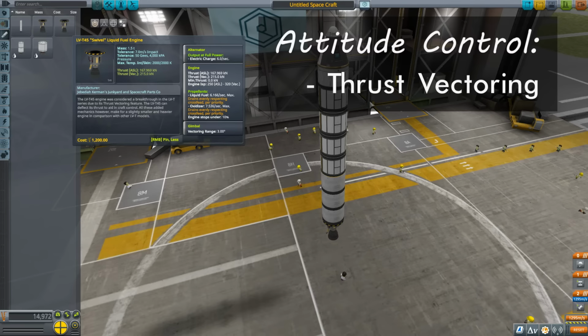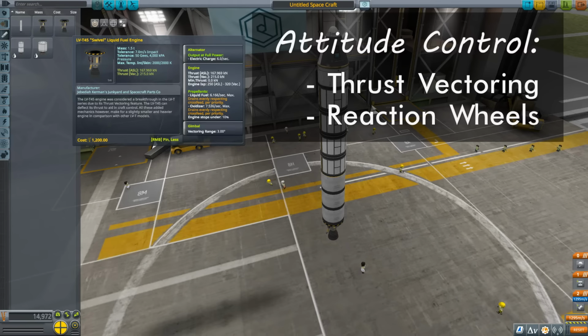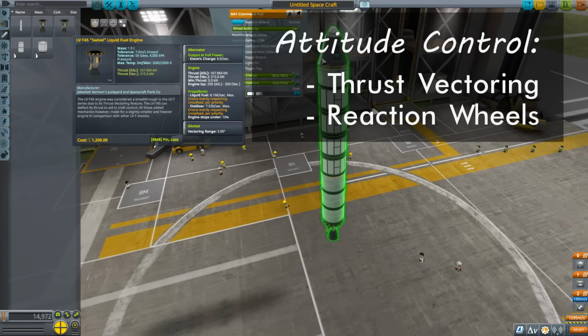Another way that you have is through reaction wheels. Reaction wheels are very heavy wheels that are spun up using electricity, and then again using electricity we change the axis of that rotation. You can move the wheel around, and as you rotate that axis in one direction, the vessel is going to want to rotate in the opposite direction. Isn't physics just wonderful? So we have reaction wheels in the capsule, actually right up here at the top. So this now has 2 methods of controlling attitude.